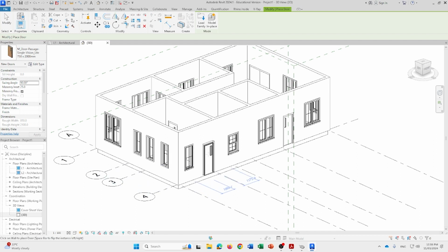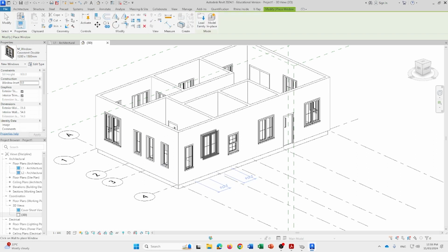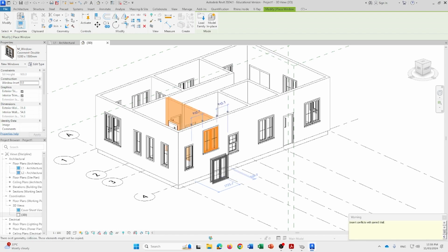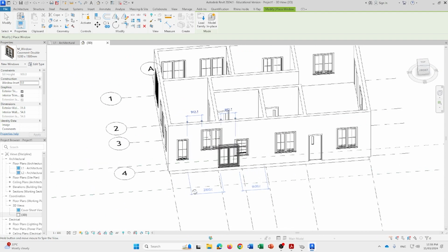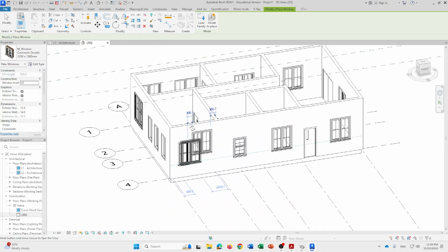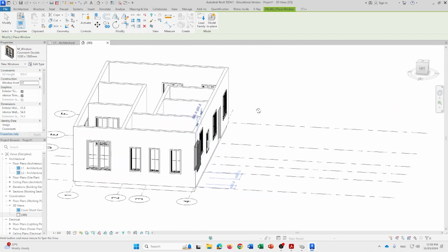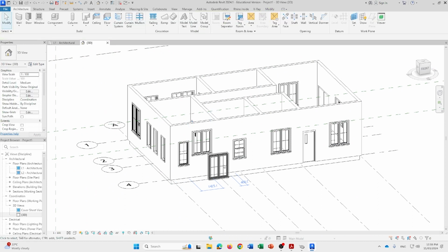Doors will snap to the actual floor level or floor plan level. But for windows, you can place them at different heights as well. Again, make sure they don't intersect with any existing walls, otherwise you'll get an error pop-up. Was there any questions before we move on?